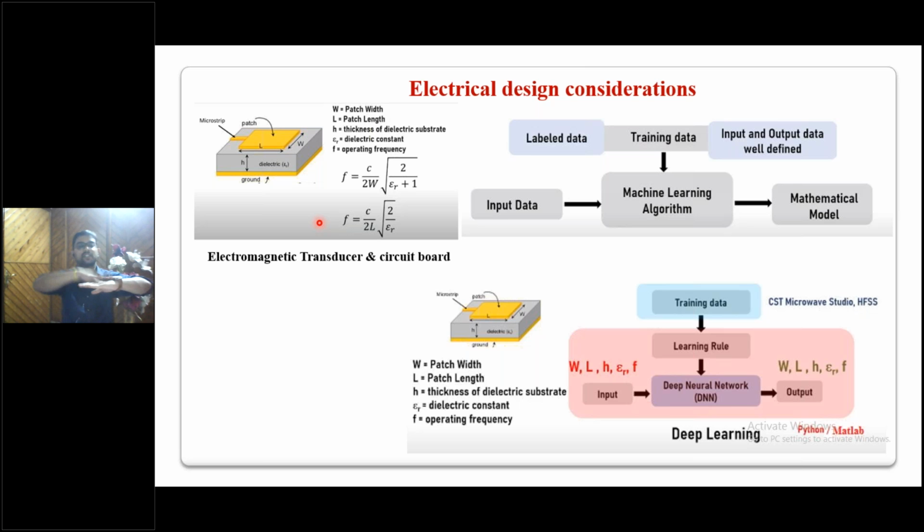So you have this fabric, on top of that the ground plane, on top of this a dielectric medium of height h, and on top of that a patch that we call a microstrip patch antenna. This is the patch, of length L and width W, and we are feeding this patch using a microstrip transmission line. So essentially this is the diagram of a microstrip patch antenna.